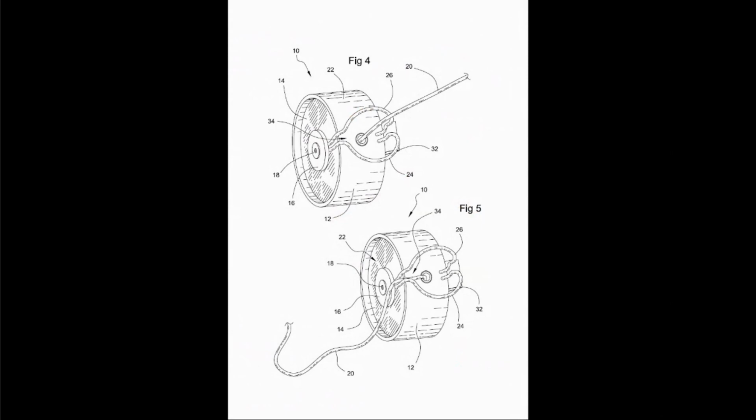So at that point, from a patent illustration point of view, you need to show an isometric view, plus front, back, bottom, top, left and right views. Those are USPTO requirements, because an examiner who's going to be looking at this in a couple of years needs to understand what it is that the inventor is trying to convey. And my job is to make sure that I present that information clearly.